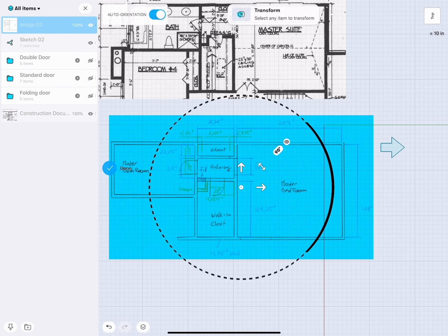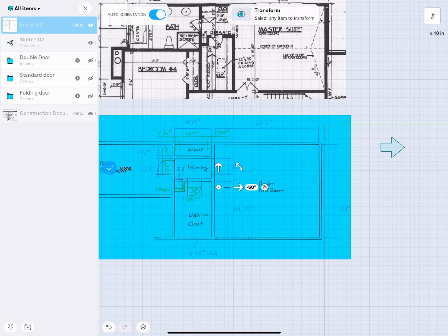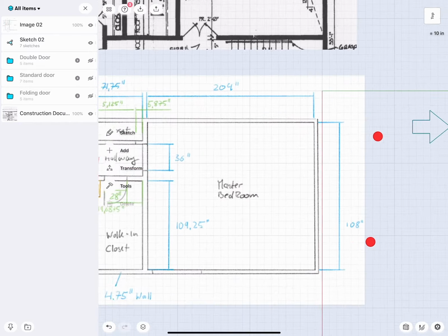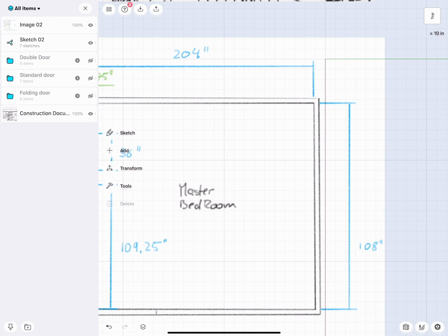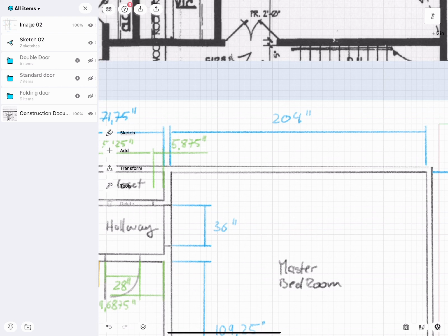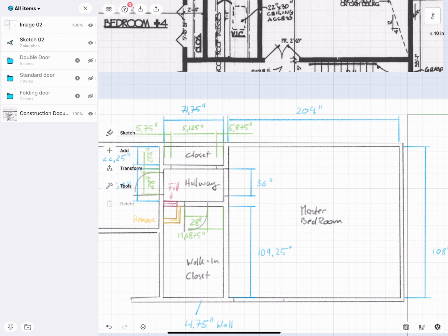There. So how do we establish scale? This is basically step number one. Inside this drawing here, you can see that the interior space is 108 inches and 204 inches wide on each side. This is also another tip: work simply in inches instead of working with feet and inches and fractions. That can make it quite difficult. Working just in inches and decimals makes it a lot easier to work between different programs for scaling purposes.